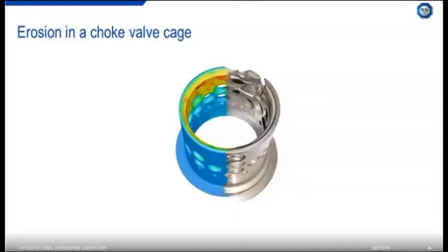One of the advantages of this is you can flow test a smaller prototype. You might have a large valve that you want to determine its lifespan within the field, but it's just not feasible to test physically. But if you test a smaller version of that and use the data to tweak and update your CFD model, so basically develop material models for that specific valve, you can then apply the CFD model to much larger geometry with greater confidence in the data that it's going to produce.